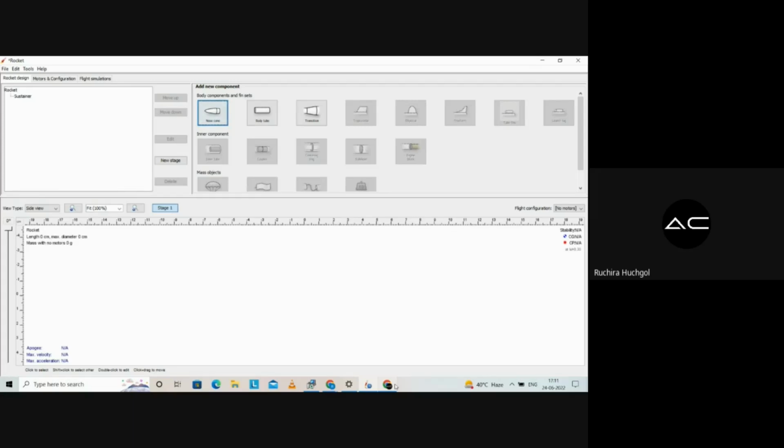Now, talking about fins, there are a number of shapes as well. There are square shaped, rectangular, elliptical, straight tapered, and then swept tapered. In swept also, you have forward swept and backward swept. But if you're just talking about the shape of the fin, then the most efficient is the elliptical one. Why? Because you must have, or if you have not, tried to get an idea about lift and induced drag.